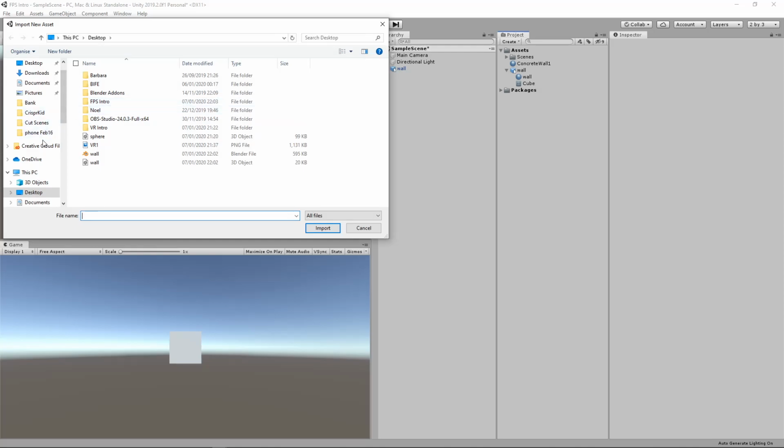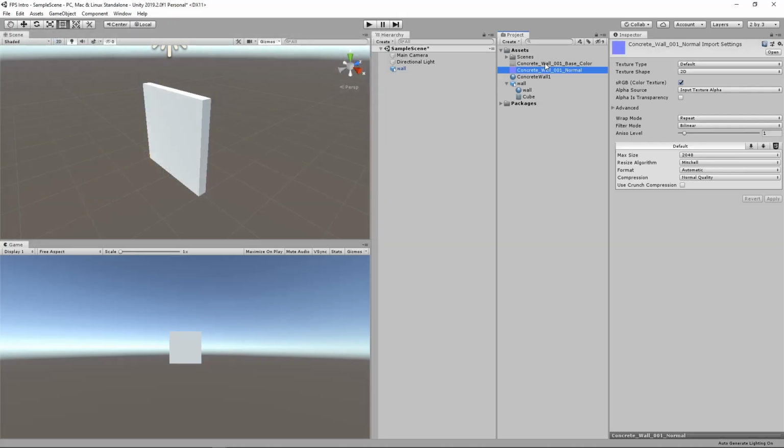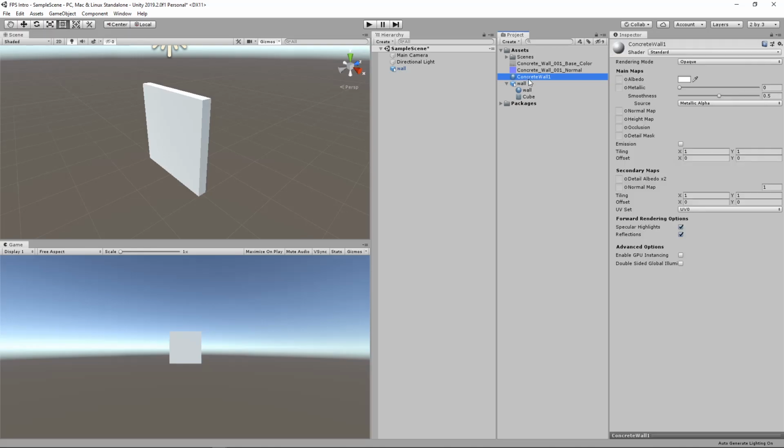Now I think they're in my download folder, so let's go find them. So here's the two of them here, so we'll import them. Now we should set up a few folders here and organize ourselves, but we have very few assets, so we'll be kind to ourselves for now and organize after we have it working. So the diffuse map, the base color map, needs to go into this first slot here, albedo.